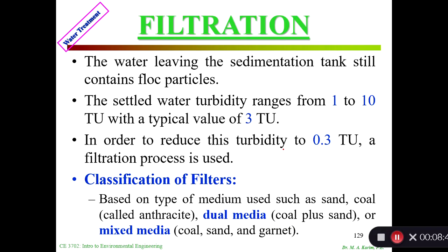Filtration, the next step, is once the sedimentation is done, then it goes to the filtration. Water leaving the sedimentation goes to filtration. There are different types of filtration we can use based on the type of media we use. You can use dual media, coal and sand, and mixed media, coal, sand, and garnet, all of those.